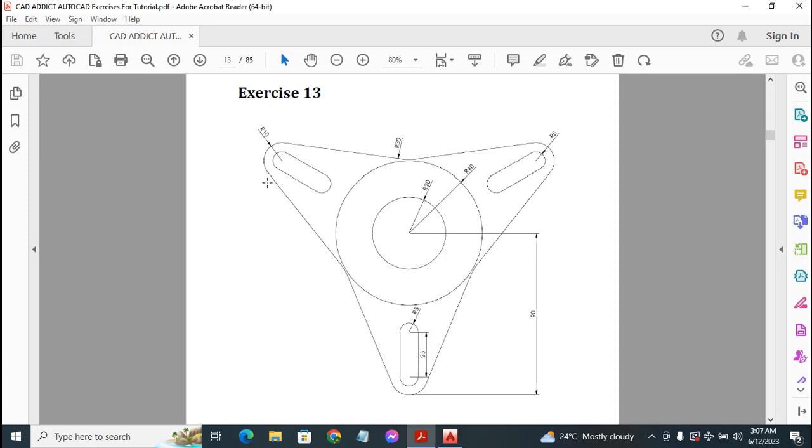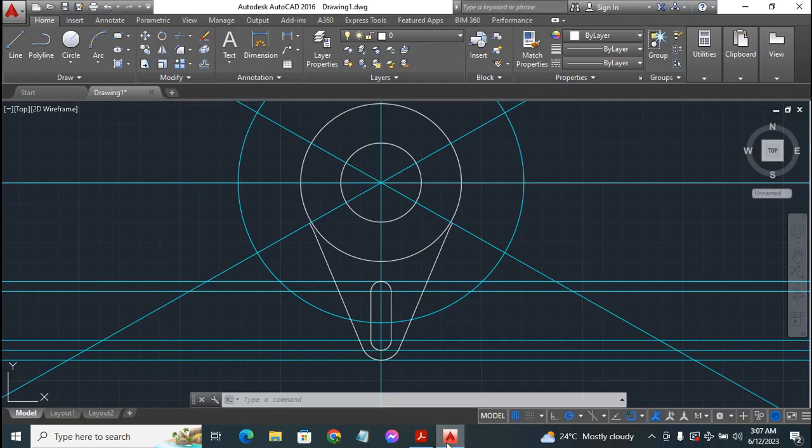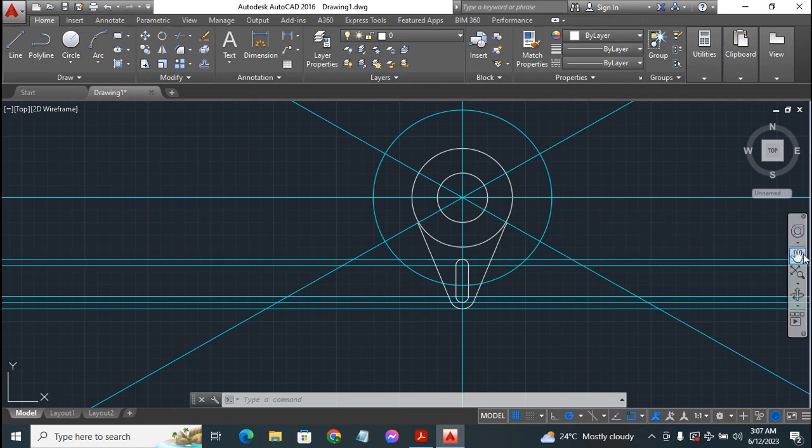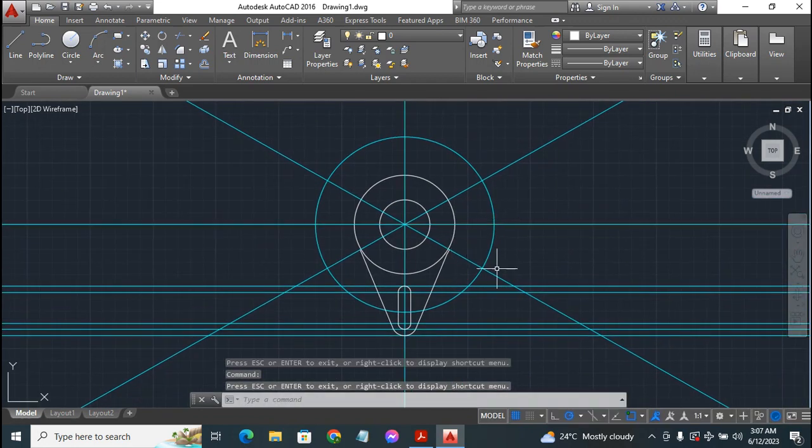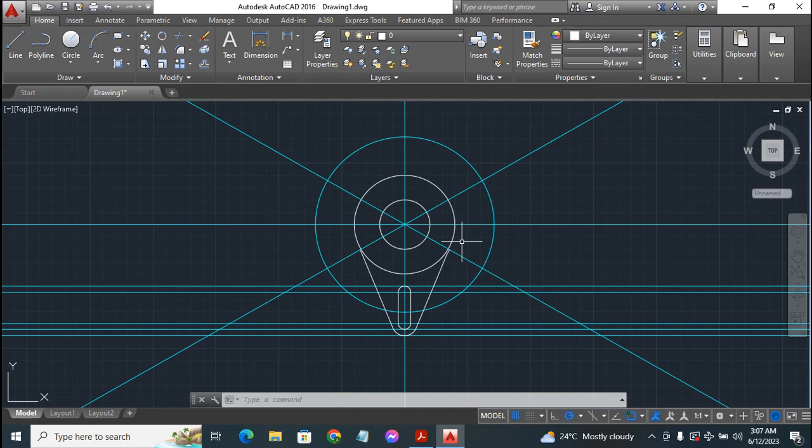So next up, you can see we have other parts right here, but to save us time, we can't go ahead and start drawing in these other parts one after the other. So we are going to use a command called the array command. As you can see, we have too many construction lines here, so I'm going to turn off the construction lines so that we'll see the actual lines we really need in this drawing.